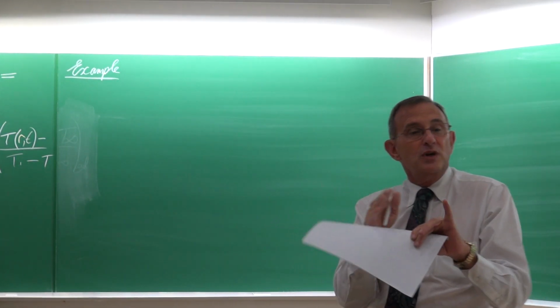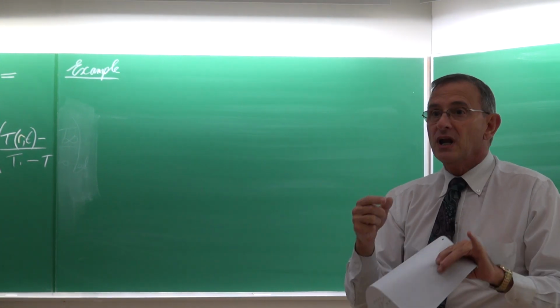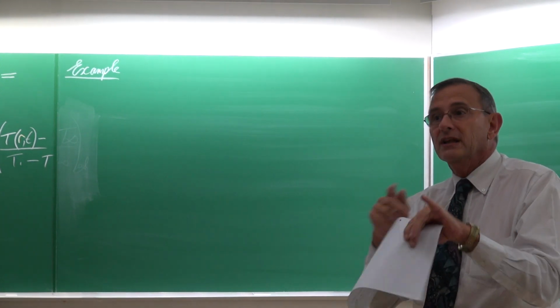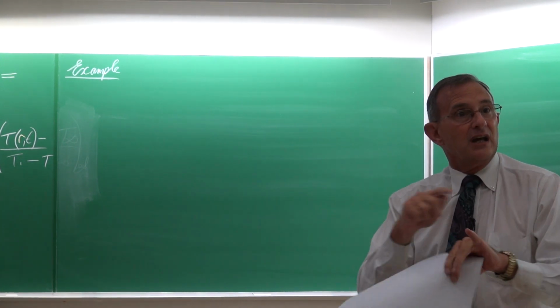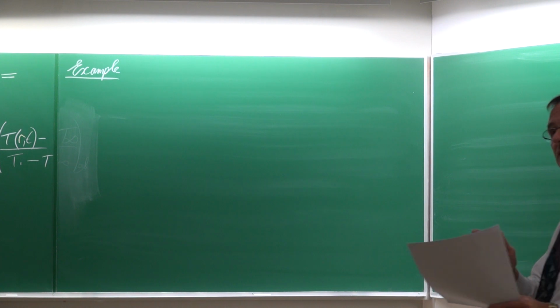approach by assuming tau is larger than 0.2. Then you can get the Biot number, and then in the tables you can go and get A1 and lambda 1, and then you have to put it into the equations, and then there's also the Bessel functions the moment there's a cylinder or a sphere. I'm not going to do it like that this year.